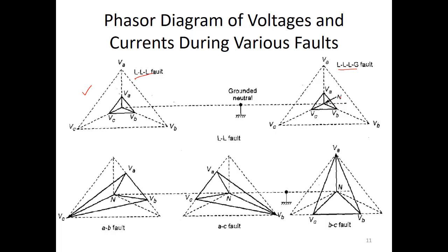You can see here a similar type of drop in the voltage, a very drastic drop in the voltage, whereas the current will increase very drastically. So we can see here that this is the 3-phase fault, or we can say the symmetrical fault. Now we will consider the line to line fault without involving the ground.